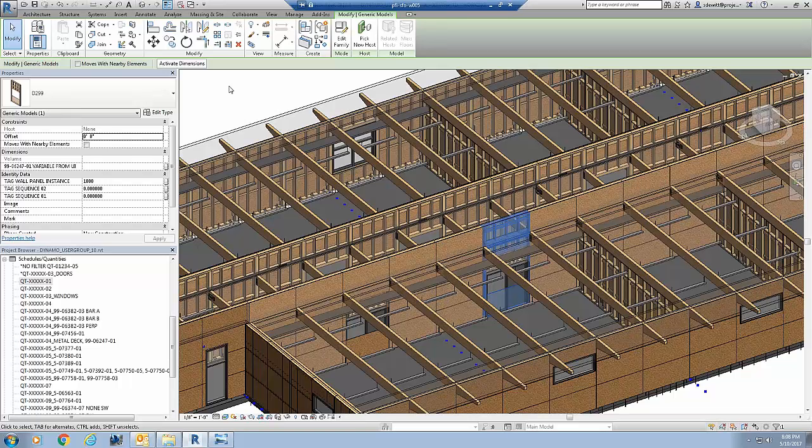That's a great question. Like I said, we've got 2 models that are being used in the real world right now. In those particular cases, we've just told them, hey, the building layout is set. Your role is to create the finishes, or your role is to drop in casework or whatever it is. So they know that they shouldn't be manipulating things. So what we'll do is actually just lock those things down. And I hate to say it, we'll pin stuff. I don't really like doing that, but it's ultimately what we have to do in order for the user to know that they are making a change that could affect the shops, or that could affect the overall layout. You can't move this wall 2 or 3 inches in any direction because it sits under the beam. It's tied in under the beam. It's where shear walls are located. You just can't do it.